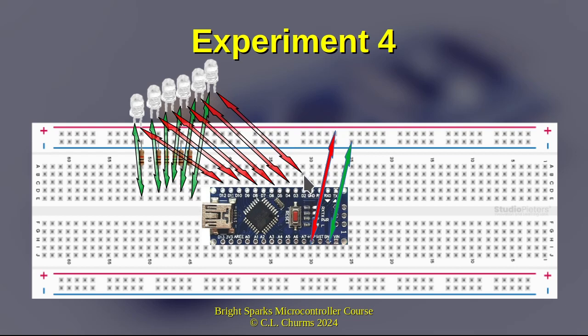And I'd like you to connect pin D2, D4, D6, D8, D10, and D12 to these 6 LEDs, and through the LED, through the resistor to ground. Fine. And then I suggested some ways to do things.